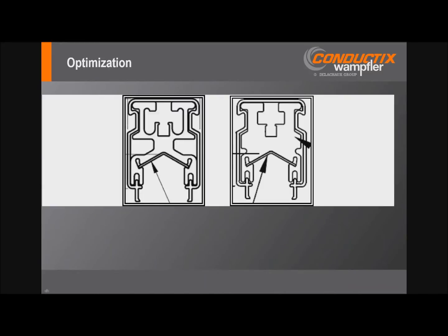An example of such optimization, these two conductors were used for the Jacksonville monorail, the Skyway, Jacksonville Automated Skyway Express. It uses both a 700 amp conductor on the left and a 1050 amp conductor on the right. The 1050 amp conductor was used only crossing the Costa Bridge over the St. Johns River, where there was a steeper incline, the vehicle pulls more power, but for the rest of the system it uses a 700 amp.